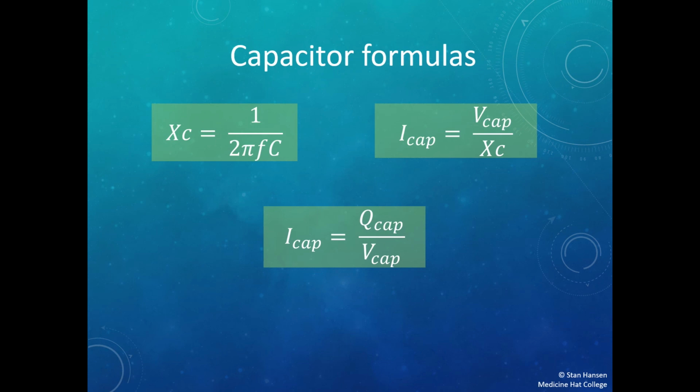If the capacitor bank that you're dealing with does not have a rated ampacity, which can happen, it will have either a rated VAR rating or a Farad rating on it somewhere. And if this is the case, we need to rely on our theory formulas in order to calculate what we need. Remember that if I have the capacitance, I can figure out what the capacitive reactance is and I can use that to calculate the current. Or if I'm given the VAR value, I can also use that in order to figure out my current as well. Make sure that you're familiar with these capacitor formulas and you know how to use them in order to find your current. And then make sure that you are aware of how to use that current rating in order to calculate your conductor size.